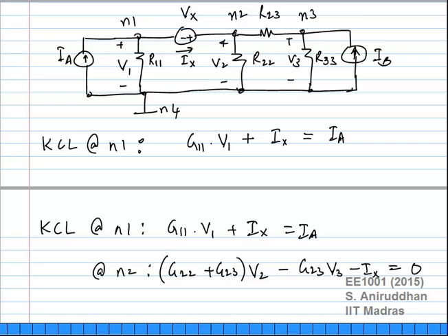We started off assuming that we are going to calculate all the voltages V1, V2, V3. So let us first do that. If you solve for V1, V2, V3, can you solve for Ix? Of course you can, because directly KCL at node 1 gives you Ix, right? Once you know the voltage variables, you can go and back calculate currents if you want to. Okay, so let us still try to concentrate on solving for the voltage variables.